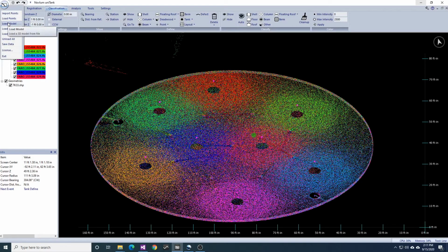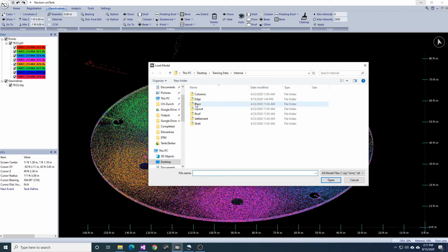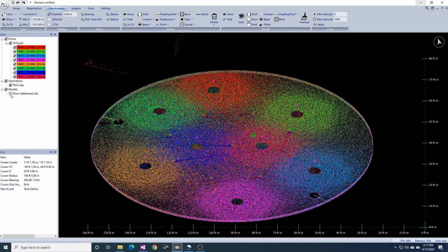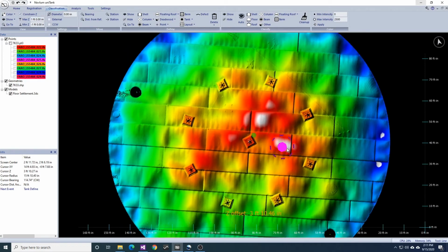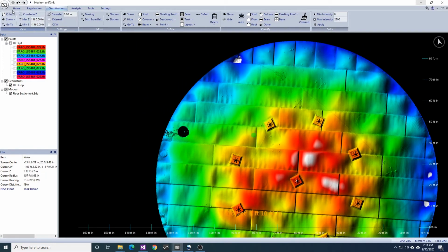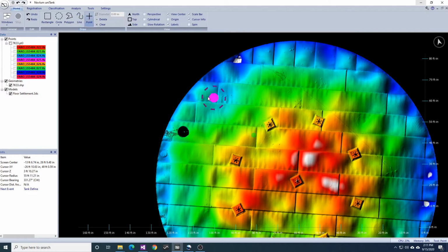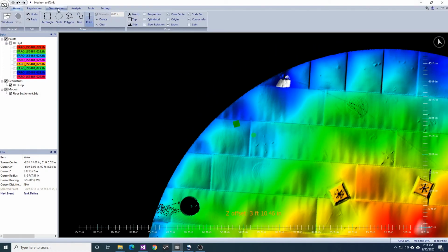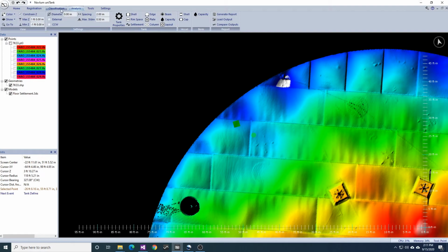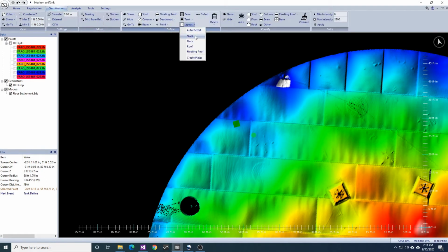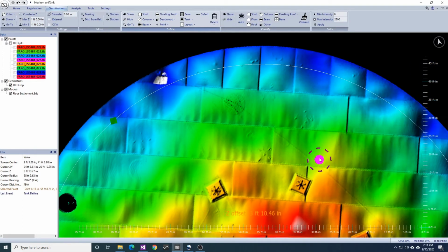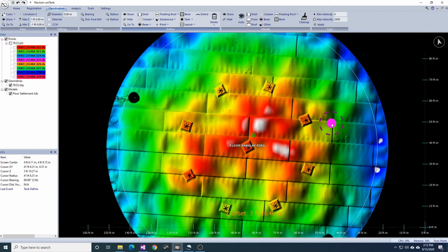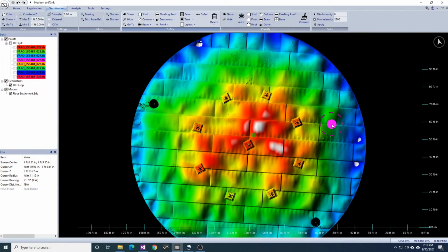First, I am going to load in the floor settlement model, which allows us to visualize all the weld lines on the floor. Note that in order to have the floor settlement model, you must have run the floor plate analysis before. If the tank has an annular ring, you can define this first. This tank doesn't actually have an annular ring, so I'm going to undo this.